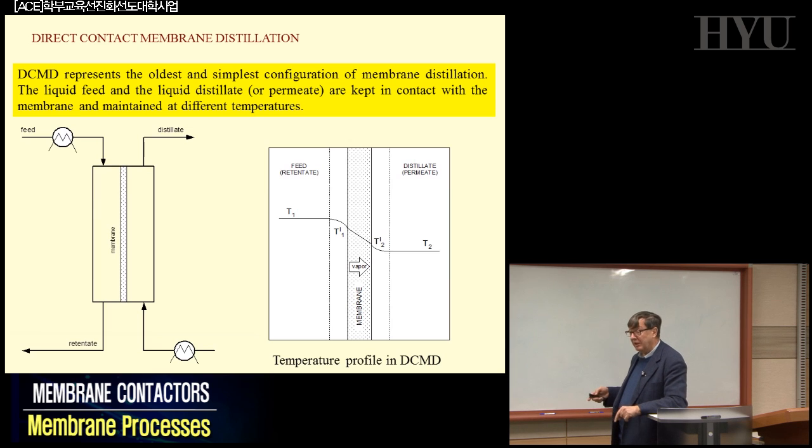Still not competing at low temperature with reverse osmosis, for example, but the big benefit, and that's why the whole Middle East is working today with membrane distillation, is that you can have this kind of distillation using solar energy. That means you can operate with systems where the temperature can be 30, 35, 40 degrees. You don't have to arrive at boiling your water, you don't have to reach 100, 120.